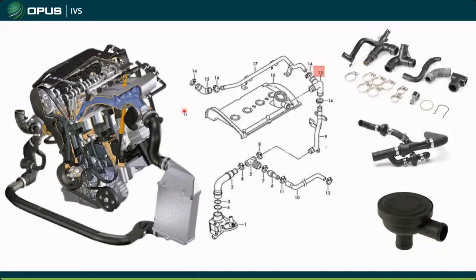And you can see this is one of the first systems here on a turbocharged engine, and you can see there are many, many components. We have a coarse oil separator. We have lots of check valves and hoses, a pressure regulating valve. These systems have just a lot of components that are all areas where things can get buggered up. We got one-way check valves. All these hoses are rubber. You'll see they get all mushy and start coming apart.